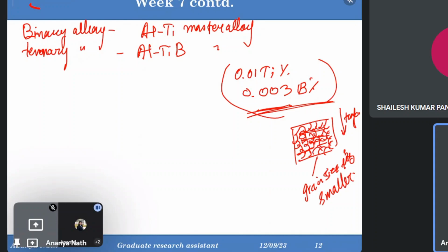Grain size is smaller. So if the cooling rate is low, means we are solidifying it with low speed, then the newly nucleated grains will have time to grow. So as a result, the size of the grains will be bigger, and the strength will decrease. Smaller grains give rise to more strength. Then, as I said, for rapid cooling from high temperature, petal-like aluminides will form. Slow cooling will give rise to plate-like morphology. Slow cooling from lower temperature will give rise to blocky type grains.